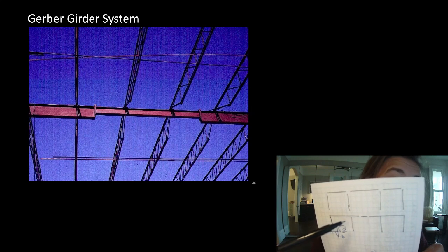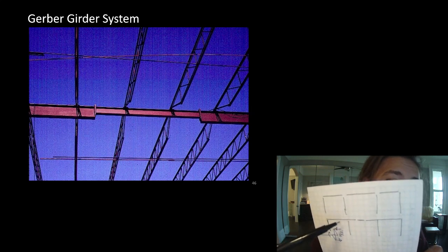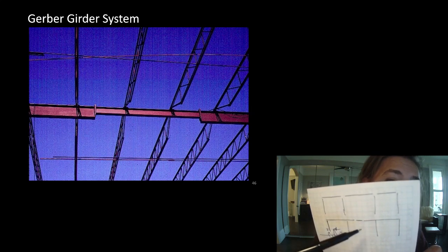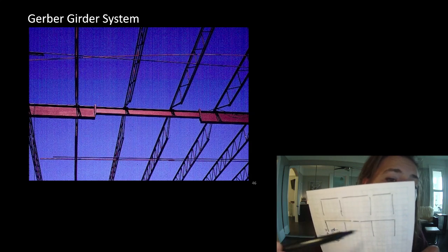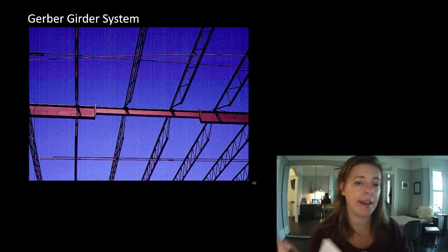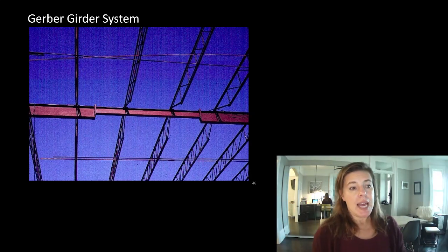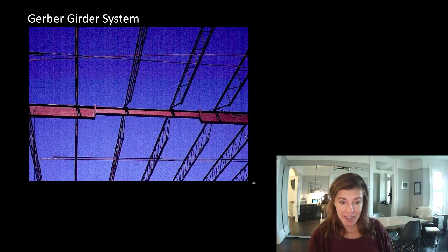Bottom one is 3 bays with 3 beams. But you see this beam cantilevers over, and this beam cantilevers over, and then we drop in this tiny little beam. What's nice is that these 2 bays can be stable, and then we just come back and drop this little tiny one in. It doesn't usually have a ton of savings in steel weight.